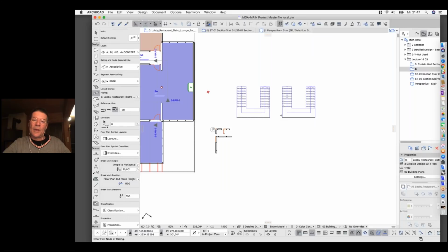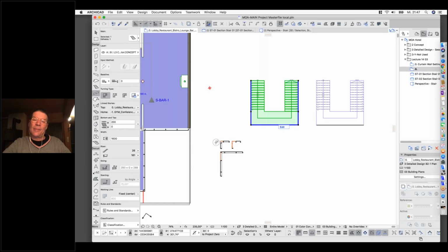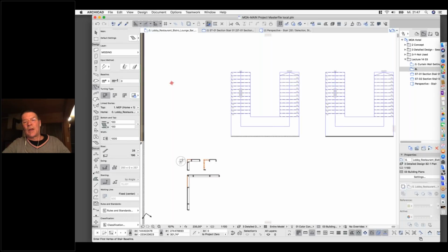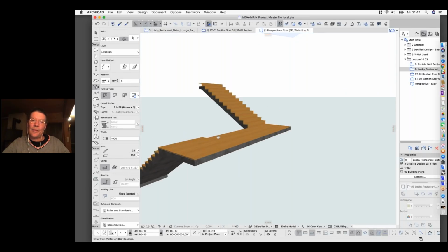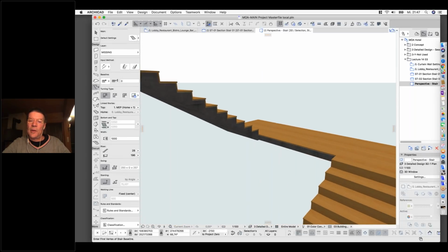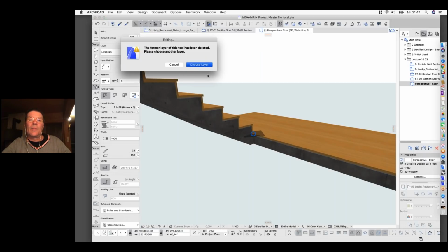Once you have done that, you can start to place a rail on your stair. At the beginning, I tried to do that in one go. I even took the settings on the stair so that I would automatically have a rail on the left and on the right, but it was a bit frustrating. So I found out that the best way for me is to start with a selected stair and to start the rail on nodes which I know.